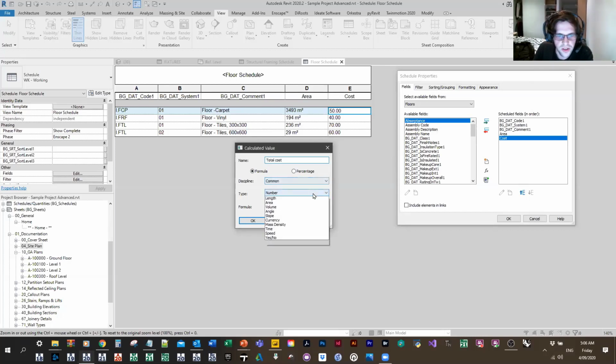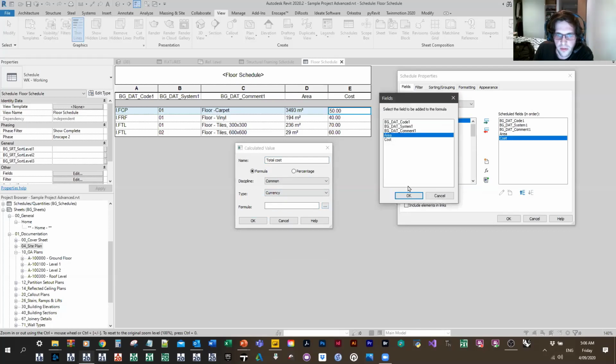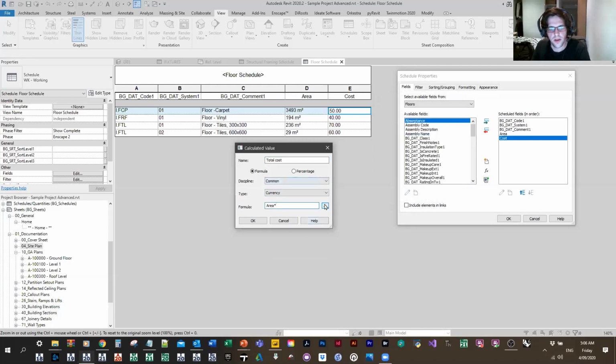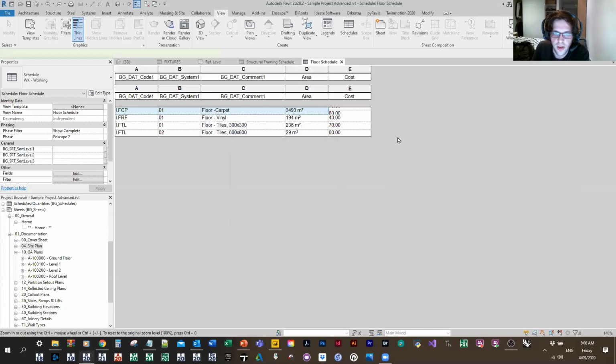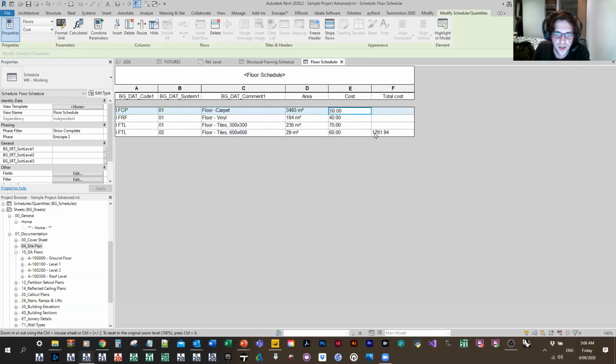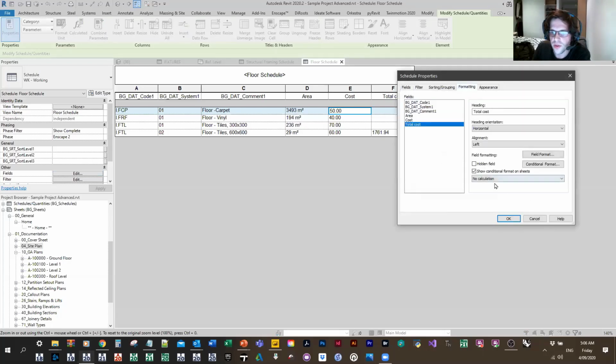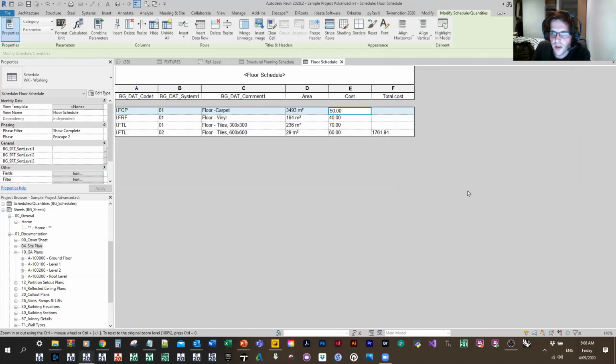And in this case, we're going to have to manage some units, which is why I wanted to show it. So we're going to be multiplying area by cost. And if you remember what happened with the beam last time, we don't get a unit that works. So we actually need to divide it by 1 meter. And we actually need to divide it by 1 meter again, because we're managing out a squared unit in this case. And now we'll get a total cost field. Again, we get a calculation on this one because there's only one of them. But then after that, we'll also just do the calculate totals. And now we have a full priced takeoff.